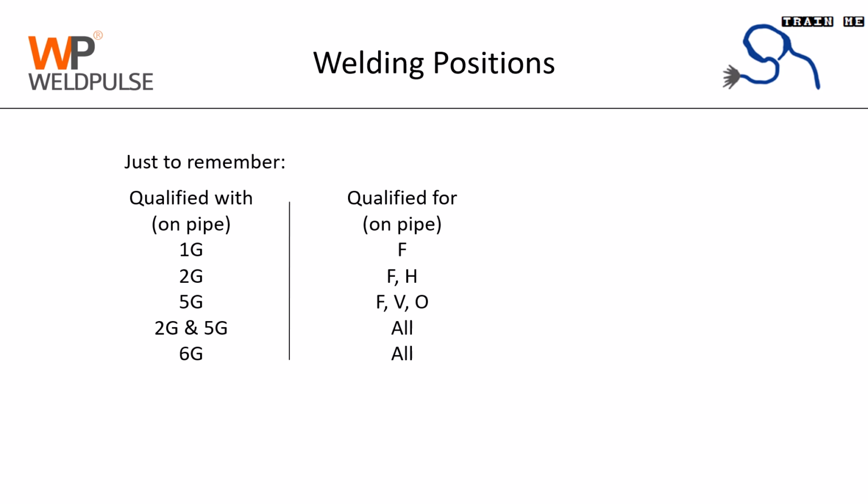As said earlier, welders are normally qualified on 6G so that they can weld in any position which is encountered on site. An addition in the welding position has to comply with these requirements. This is an essential variable for welding performance qualifications. However, position is not an essential variable for welding procedure specifications.